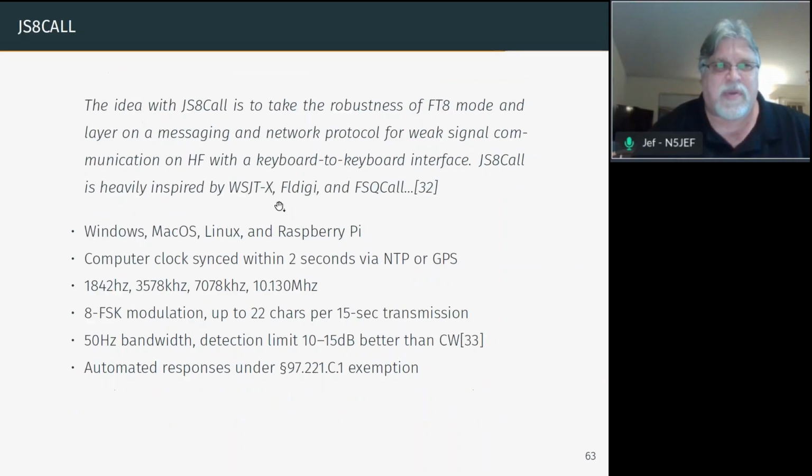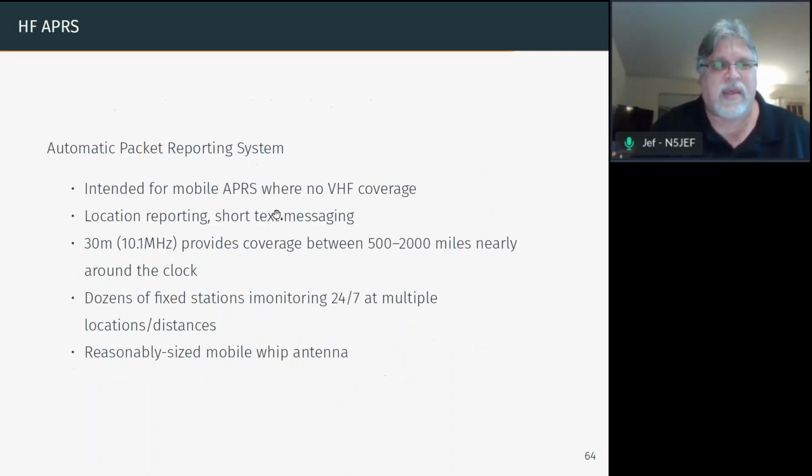Now that's been replaced with JS8Call, which is even more robust. And this goes to Greg's question about power. If you're going digital, Greg, you can get away with just a few watts and still have very reliable communications digitally on NVIS. And then there's HF APRS. I mean, a lot of us have seen APRS on 2 meters.